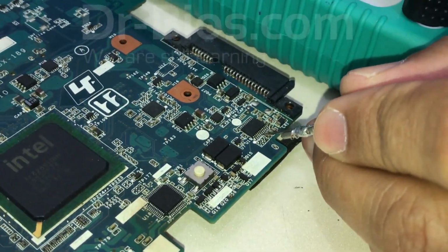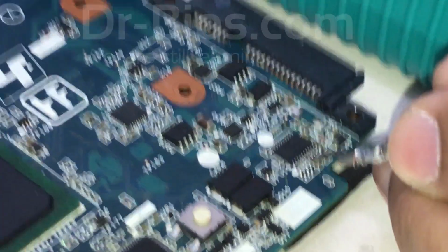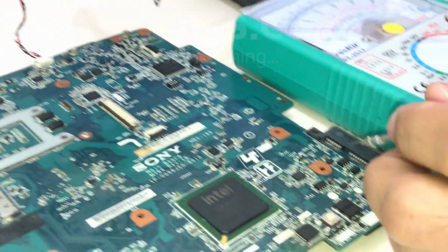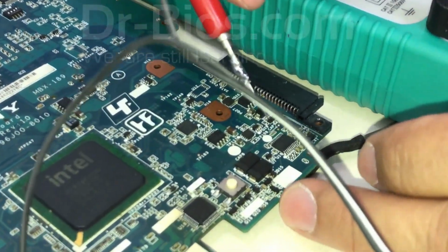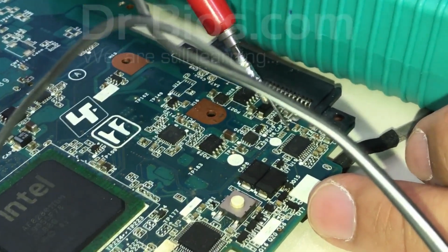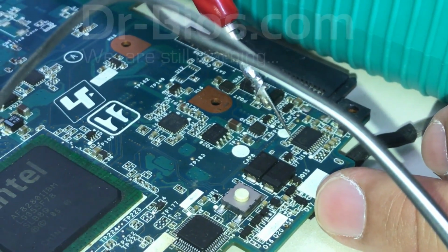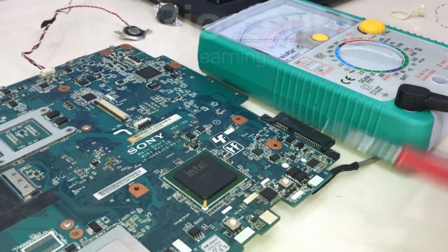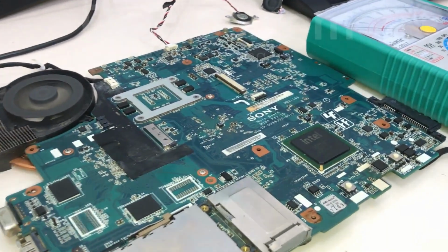Pin 5. You can hear it easily. It was the left direction. Now I test the right direction. Pin 17. Yes. So with this sound test we realize that the amplifier is okay, so there is no need to check the voltages of the amplifier now.